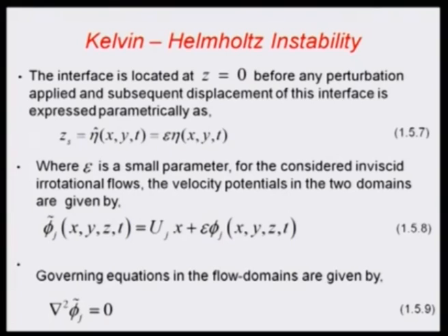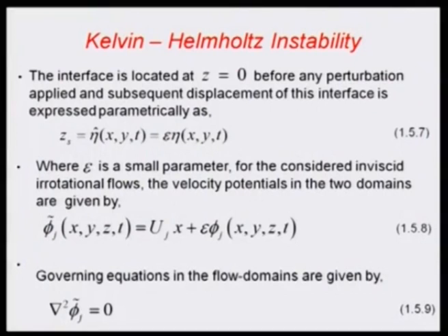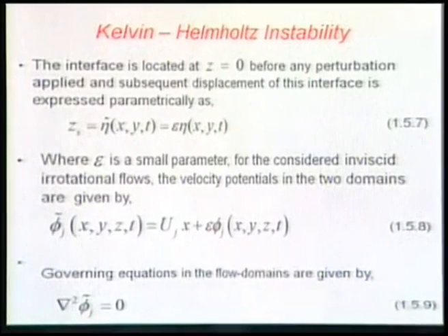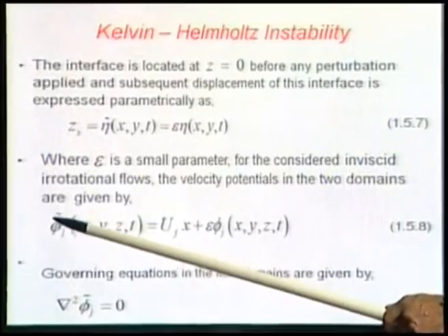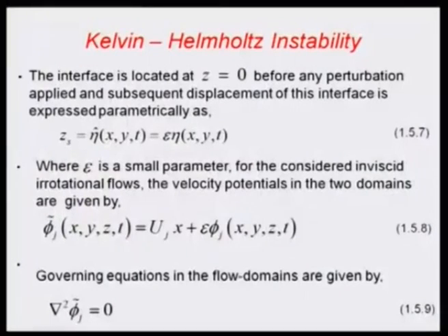right. So, what happens is I can see very clearly that the governing equation for this disturbance potential is simply nothing but given by the Laplacian, because you are talking about inviscid irrotational flow, right. That is what it is. You take its second derivative, this does not exist. So, this part is automatically a solution of phi. So, del square phi tilde is equal to del square of this quantity. That is what we are going to see.